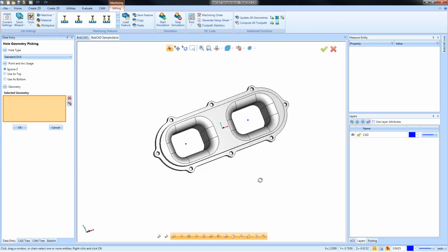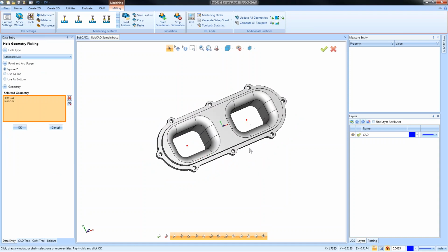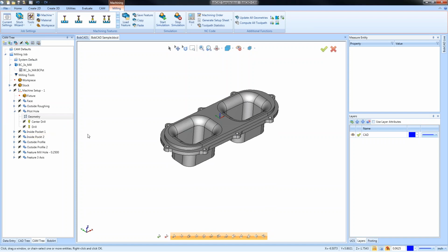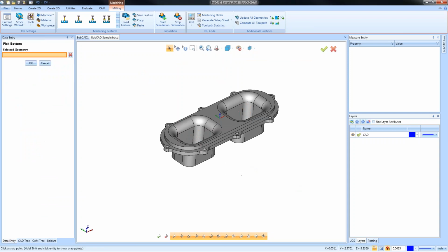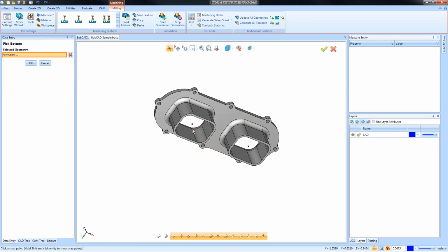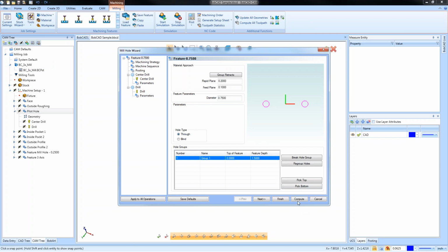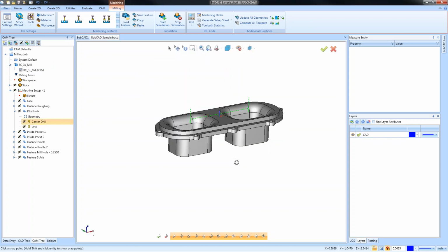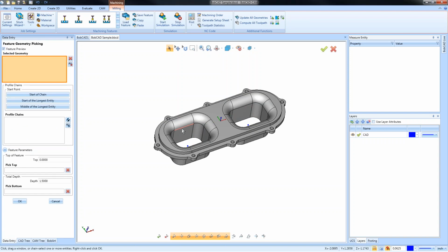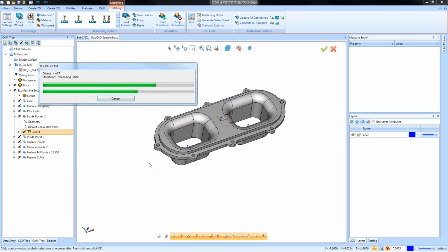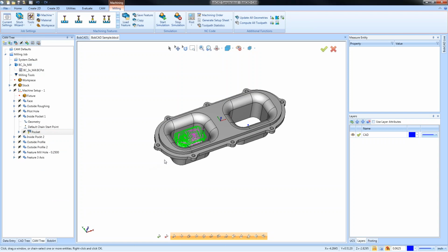My next step here, I want to drill a pilot hole, right? Now, not everybody will start with a pilot hole, but it's also common for you to come in here and maybe drill a pilot hole, saying this is where I want my tool to start from for like a pocket routine or something like that, right? So, okay, here we are, we're spotting, we're drilling. Okay, the next one here is this inside pocket. So what's really cool about these CAM tree templates is you can set up these settings here, and then really the machining process becomes more of a selection process, right?